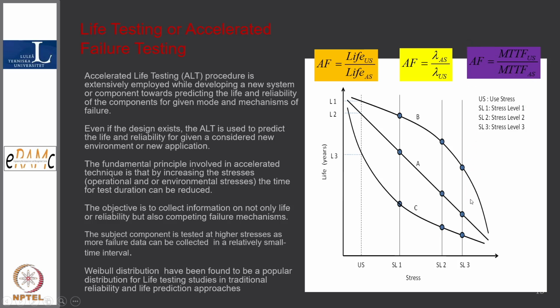So in a nutshell, life testing involves testing of the components which have been designed and fabricated under higher stress at 3 stress levels, so that we can get a curve actually. With the 3 stresses, we will derive the acceleration factor that we use to characterize or investigate the failure mode or failure types. And here the Weibull distribution has been found to be very, very useful for life tests.